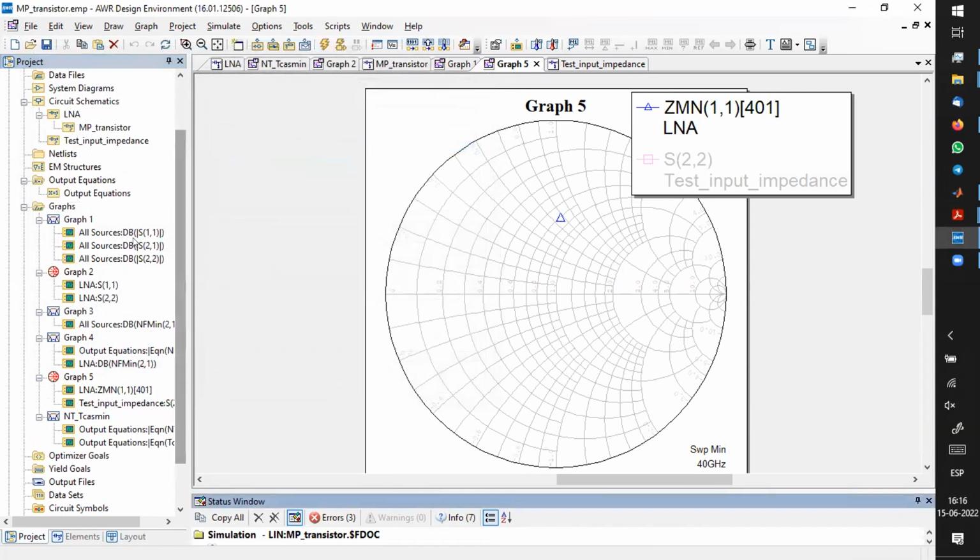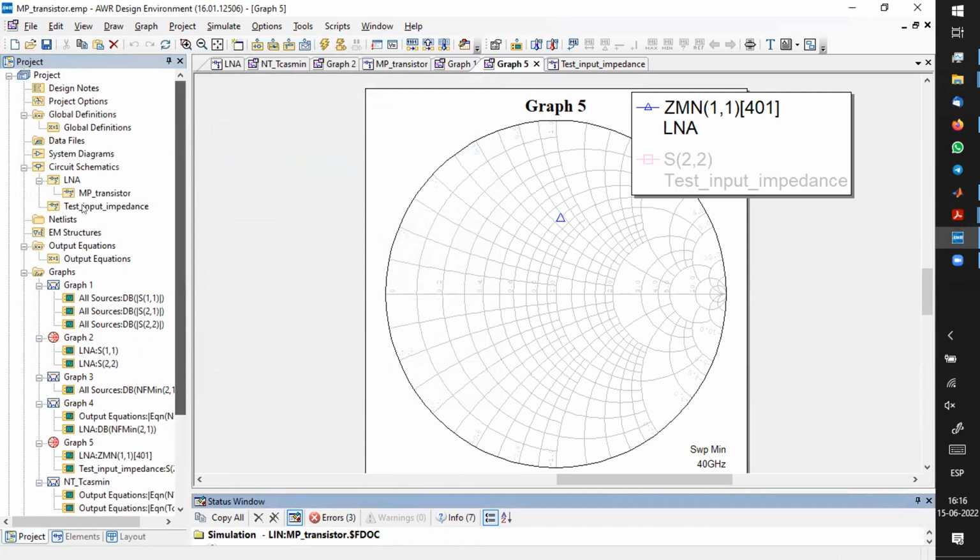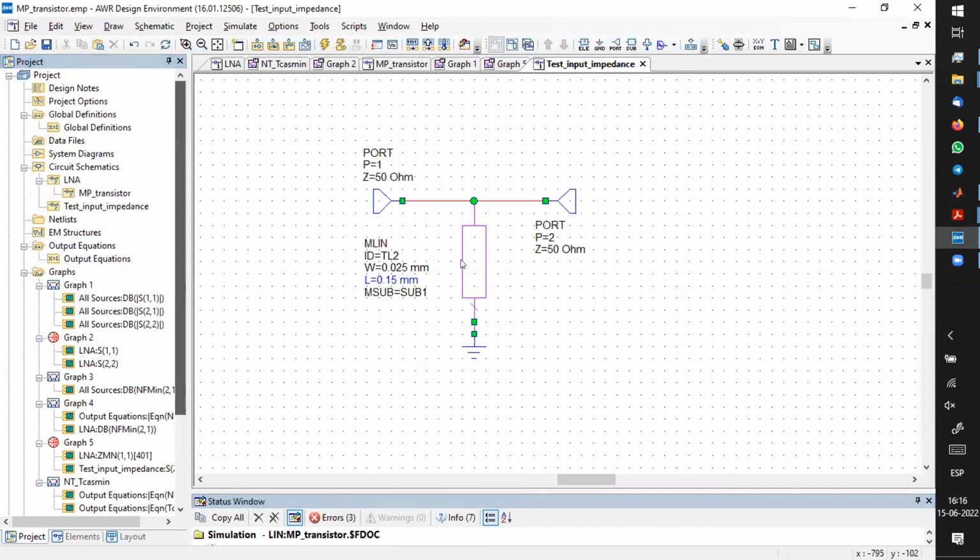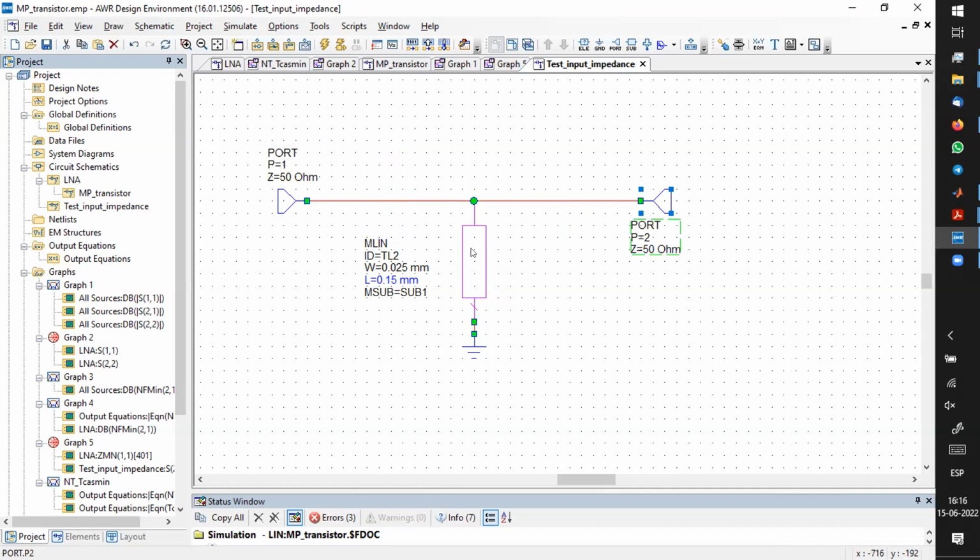So you need to add a piece of a line to the input first, because they are now short circuited. Just tell like a 50 micron line there. No, only at the input. Okay. That doesn't need to be tunable. It's just a line.